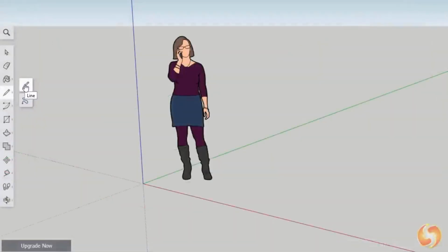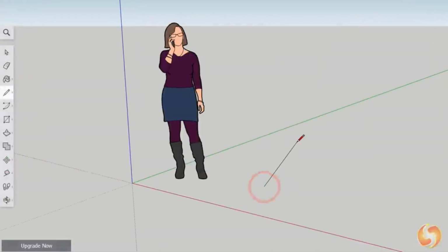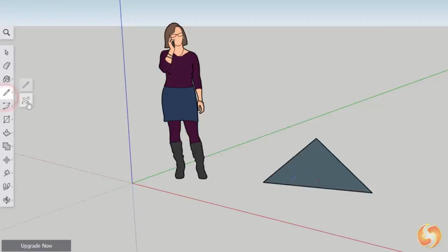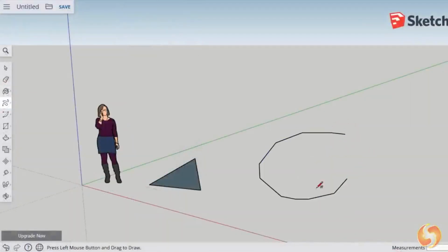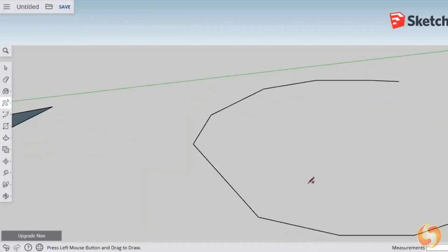Enable the Line tool to drop straight segments, sharing the last node. You can go on drawing until you use the Escape key or close the shape in progress, which gets filled automatically. You can also draw freehand with the Freehand tool, using your mouse wheel to zoom in to make lines and curves more precisely.